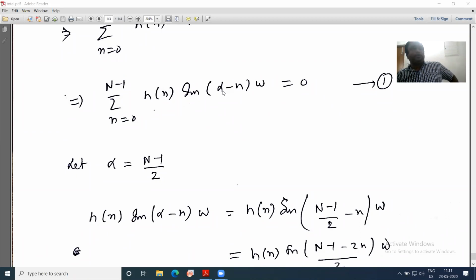From a mathematical point of view, if you look into the equation, this equation has infinite solutions. But those solutions usable for designing a filter, for practical design, are those which are related with some practical parameters. Now a design parameter is given, N equal to say 10. So this is my known parameter. We have to design a FIR filter with 10 samples. Therefore, a known parameter I am trying to relate to. Agreed? Yes, sir. Fine.